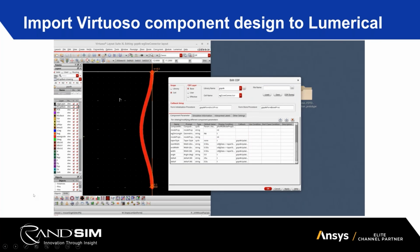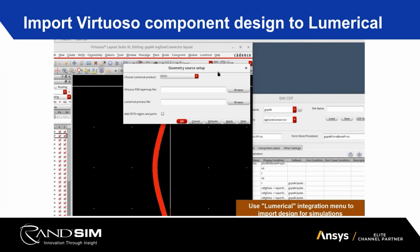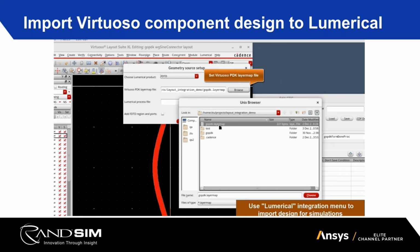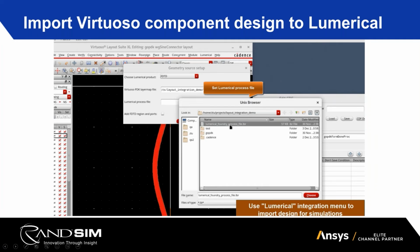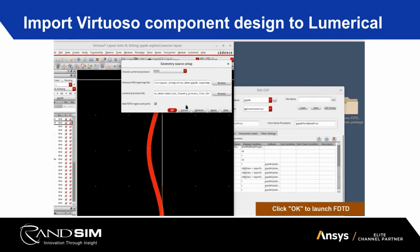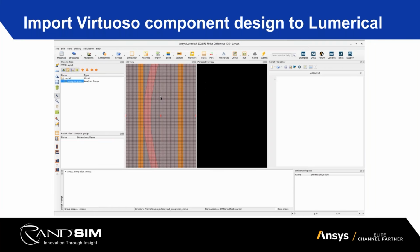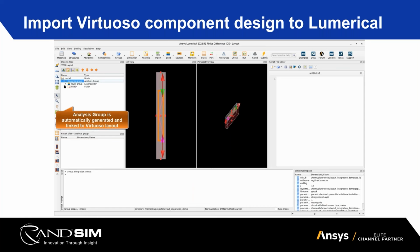So this starts from the Curvy Core. There is a Lumerical button here, and you can choose to export the layout to the multiphysics tools. And you can load a layer map file, which defines the layer material and the layer thickness. And then you can choose to load a process file if you have one, that is from the foundry. So you can define some process information. And if you check the box for getting the simulation region and ports, it will automatically define them for you.